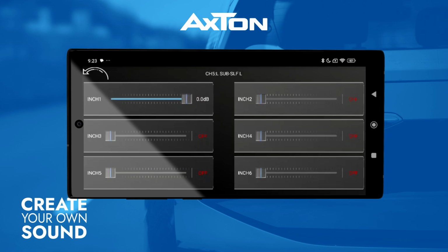If it turns out later that the subwoofer distorts due to a high input level, the input levels of both channels can be adjusted accordingly until the desired result is achieved. The other channels are again moved to the left or set to a minimum. The same procedure applies for the right subwoofer. A mono subwoofer is set up similarly to a center speaker, but configured specifically as a subwoofer.